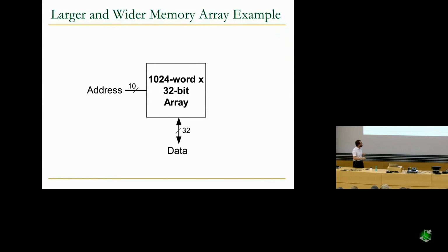In fact, that's how you reduce latency. You don't build a 1024 32-bit array. Maybe you build 10-word arrays and have 100 of them, and each of them may supply, I don't know, 1 bit, and you select the right ones. That's how you can actually simplify the design. There are many, many ways of simplifying a larger array into smaller subarrays. Of course, this is a toy example because 10 is nothing, right? We're talking about terabytes and terabytes of memory. Clearly, you don't have 10 over there, right?